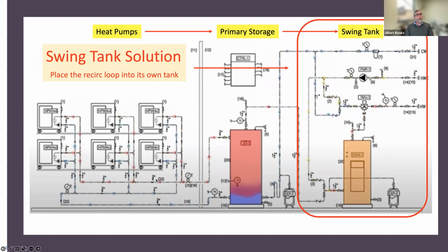When there's no draw in overnight conditions, essentially what's going to happen is that tank's going to cool, because we gave that tank full 150-degree water. It takes that 150-degree water and starts giving it to the building through a mixing valve. So we mix it down to 120 or whatever number, we send it out to the building, and when it's used, it just goes away. It goes down the drain, no problem. More cold water comes in and replaces it.